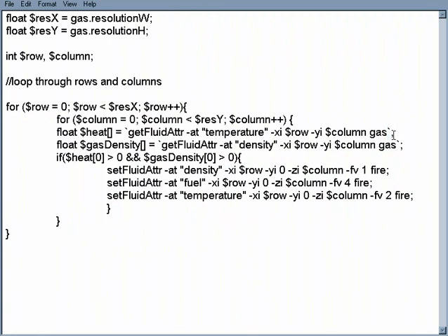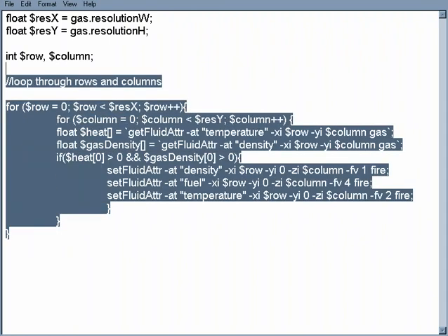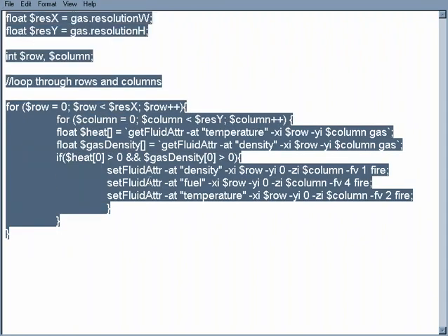Now, it looks like these are just the little quote marks that are next to the enter key on your keyboard, the little single quotes. But these actually aren't. These are what's called a back quote. The back quote is found on the tilde key next to the number 1 on your keyboard. So it's very important that you use the back quote that's on that tilde key and not the single quote that's next to the enter key on your keyboard when you're making this. Otherwise, the expression is not going to work correctly.